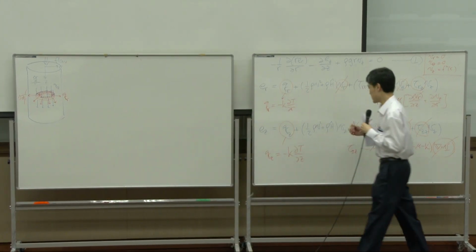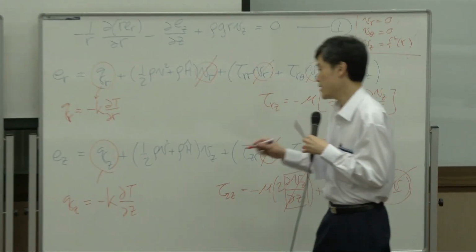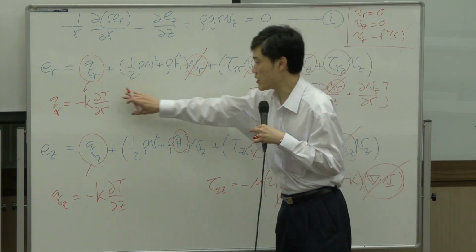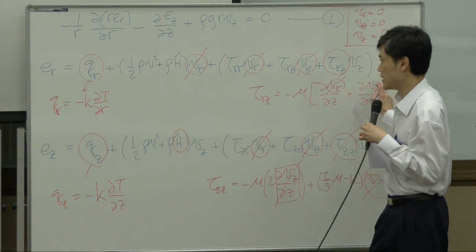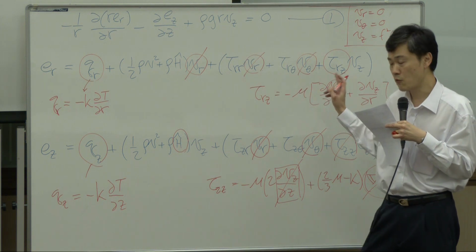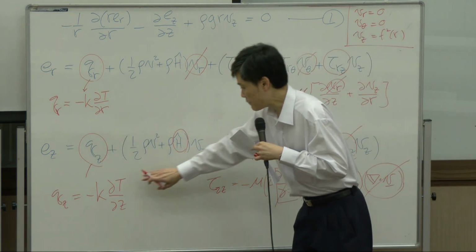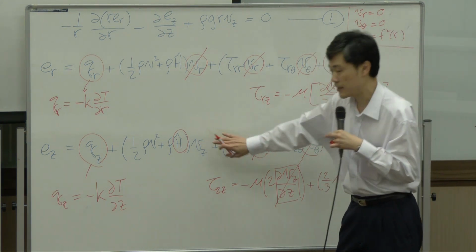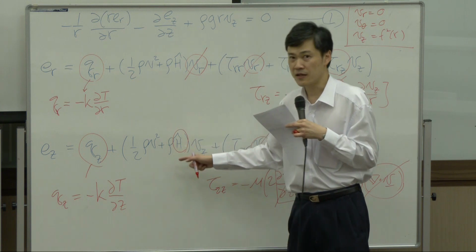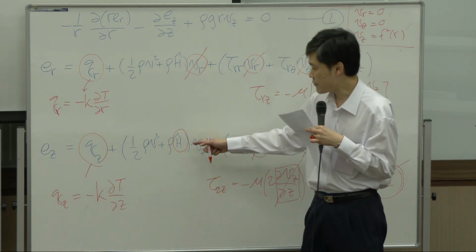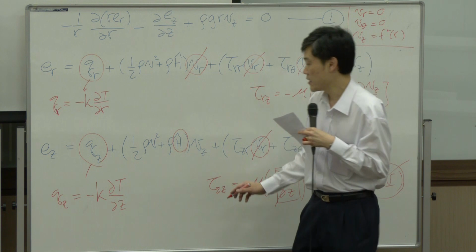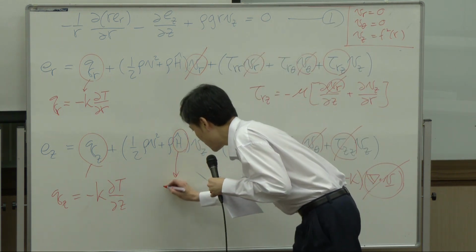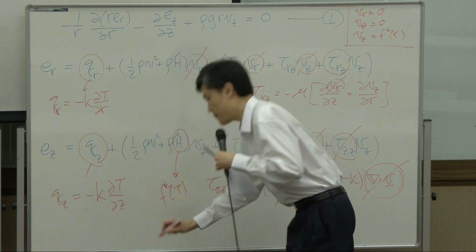The problem in this second part of the flux is enthalpy. Okay? First part, there's no problem. Temperature is measurable. Velocity is measurable. Both of them are what we want. The second part here, we have temperature, that's fine. We have velocity, that's also fine. But enthalpy, this term is a little bit abstract. We cannot measure enthalpy. But according to thermodynamics, we can change enthalpy into the function of temperature.